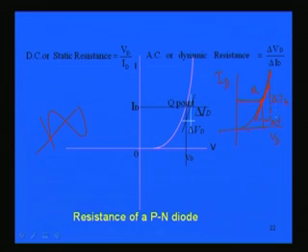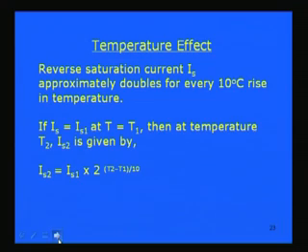That is, dynamic resistance is given by del Vd by del Id, called dynamic resistance or AC resistance, because you are operating the diode under a signal which brings the current and voltage to this point, as well as the other point, since it is a sinusoidal or varying voltage, so we have to find the dynamic resistance of this diode.